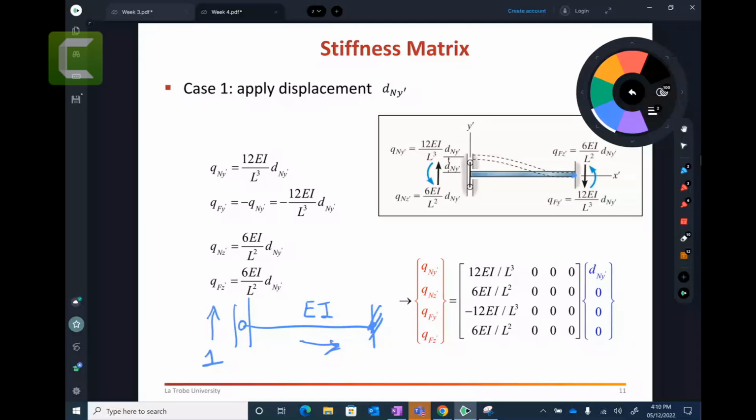Some, when you pull it, it's still very difficult. That is a Young modulus. You put it in a machine and you can draw the stress strain curve, and the slope that you get is the Young modulus. It's just the measurement of how stiff the material is. How stiff meaning how stretchable the material is. So that is a Young modulus, right?